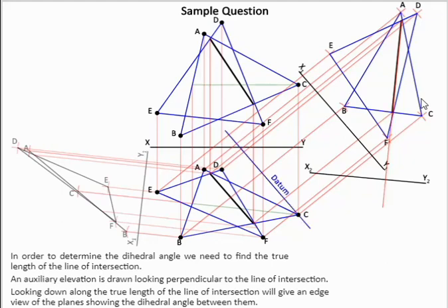Now we're using a datum line in this case, and the reason for the datum line is just to cut out all this space here, because remember, to find measurements for x2, y2 auxiliary, we go to the previous xy line and measure back the way, but we're measuring a lot of empty space here. So if we use a datum line here, we can measure from the datum line and get the same end result. The only difference on our page is our answer is going to be next to our x2, y2 line rather than down low on the page.